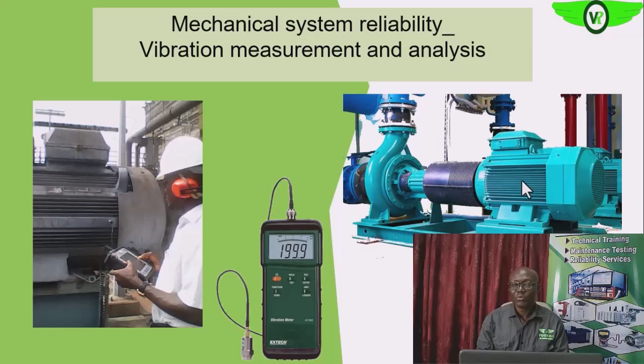So that component has a way of affecting the operations of the electric motor if it is bad. Then the rotor itself, remember, it is expected that it will be rotating constantly. We also see some of the things that can affect it, like unbalance, that will affect the operations of the electric motor mechanically and thus the entire electric motor system.